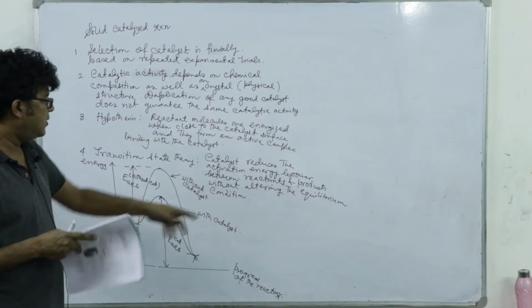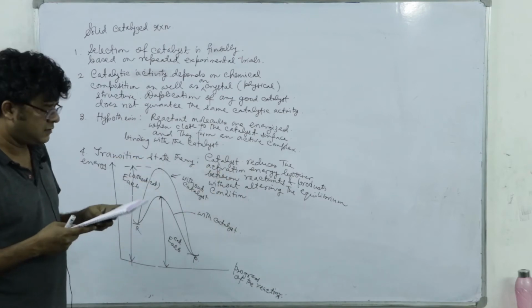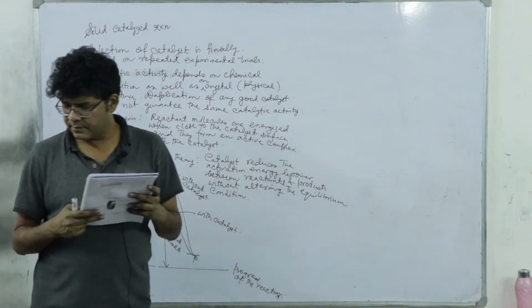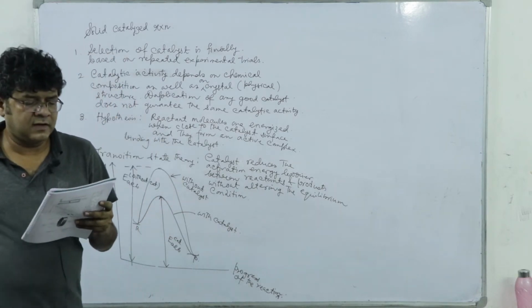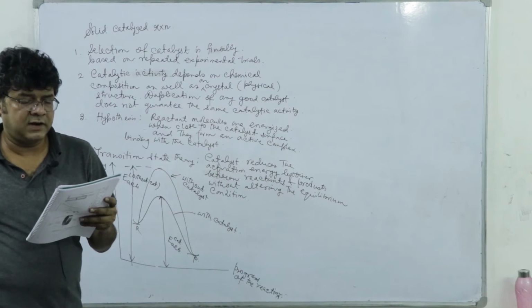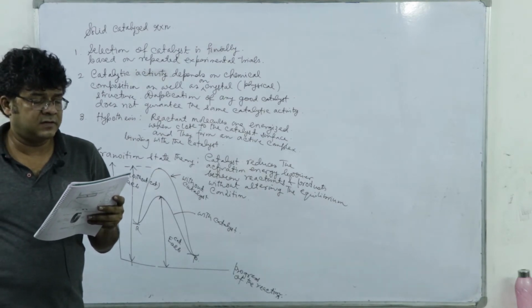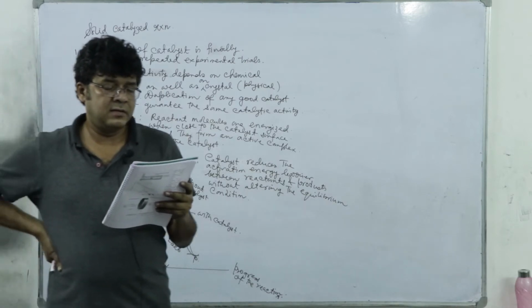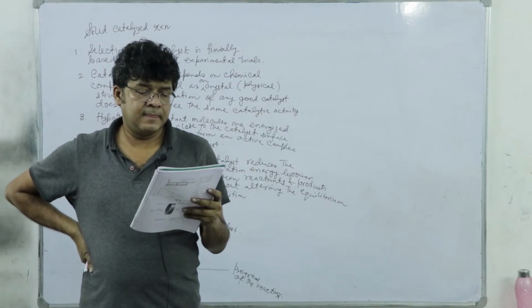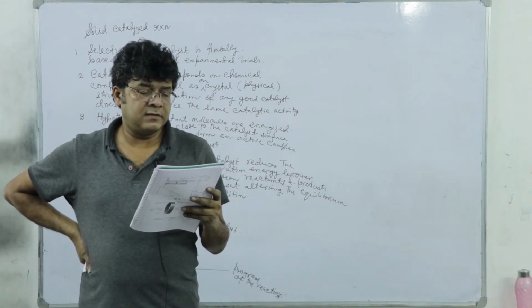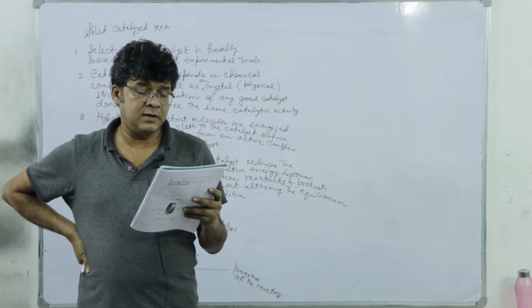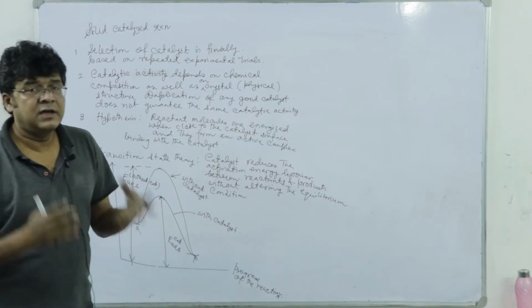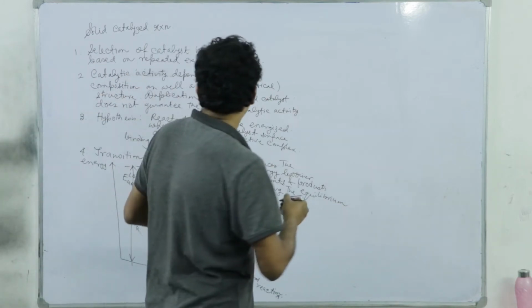Now, we have already mentioned that it is not altering the equilibrium. So, next, since the surface is responsible for catalytic activity, a large, rapidly accessible surface of easily handled material is desirable. By a variety of methods, an active surface area of the size of a football field can be obtained per unit cubic centimeter of a catalyst. So, it must have a porous structure.